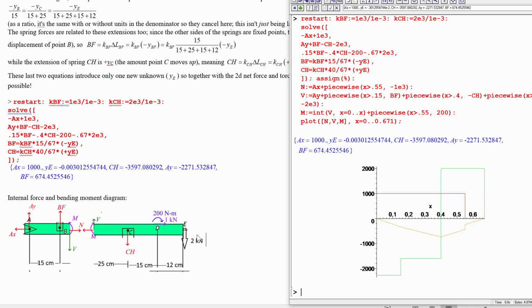And then we cross the last point here, and once we cross the end point, that returns us back to equilibrium because there's no more forces on this, right? We would have solved exactly the same problem if the beam didn't stop there, but instead continued and had no more forces applied on it. So it needs to return back to 0 because we don't have any more internal force or moment. Okay, and same thing for the moment, right? The moment starts off here. There's no point moment applied at either end, so it has to go back to 0 at each end.